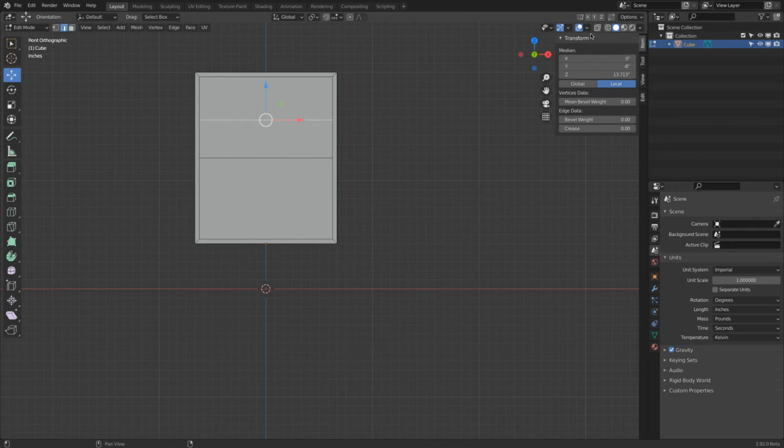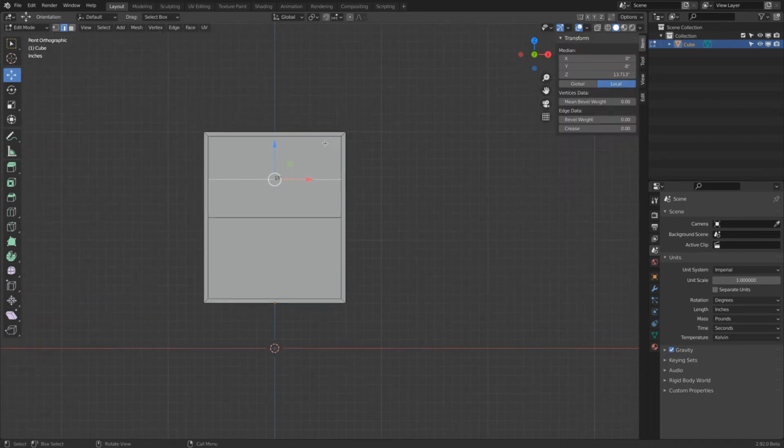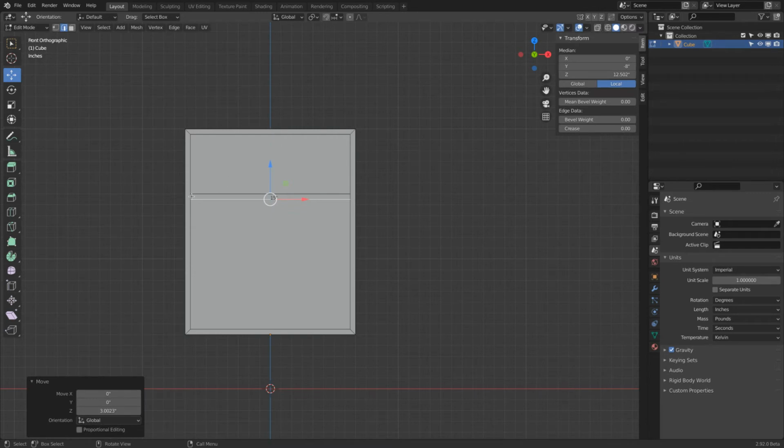There are two ways how we can do this. A very quick way: we simply turn on our measurement as that overlay. Then I select this edge and move everything up and down, hold Shift so I can do these commands a little bit more fine, and pay attention to the length of my edges. Hold Shift there. So this is now 0.5 and this is 5.5.